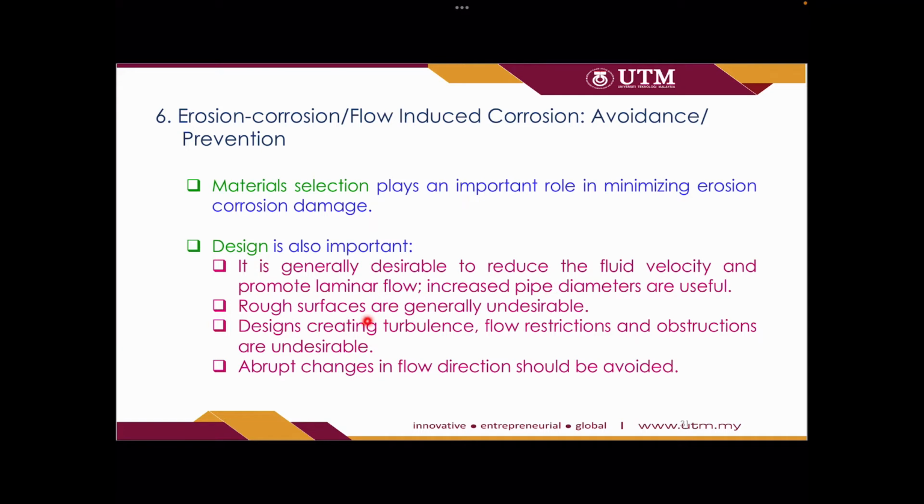Rough surfaces are generally undesirable, because a rough surface will interrupt the laminar flow of the liquid or gases. So design creating turbulence, flow restriction and obstruction should be avoided, and abrupt changes in the flow direction should also be avoided. Just slight changes or a smooth curve, rather than a sharp curve, is preferred.